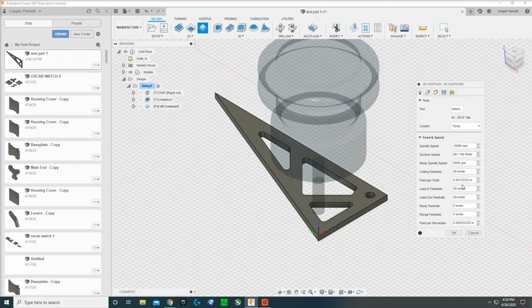And so that's the main reason why I do a separate toolpath instead of just the smoothing feature of the 3D adaptive clearing before the pocket, because we can now control this feed per tooth, which means a smaller feed per tooth, as you can see, means a much smoother cut, less vibration generally, less aggressive, smaller chips, which is more controllable, all those good things, which, yes, take longer, but for a bearing hole, I always do this second toolpath with the 2D contour.